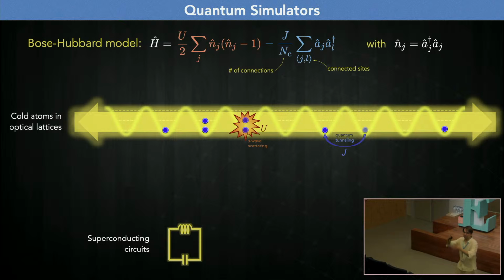This is one of the first things that they tell us, and they give us a lot of exercises about the harmonic oscillator in LC circuits, and so on. So essentially, we know that an LC circuit effectively is like a harmonic oscillator, where you have a periodic exchange between the energy stored in the capacitor and the magnetic energy stored in the inductor.